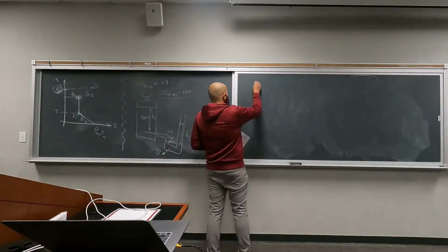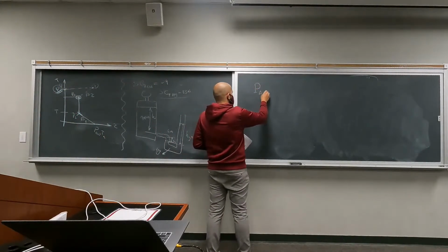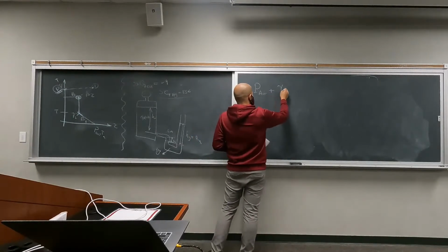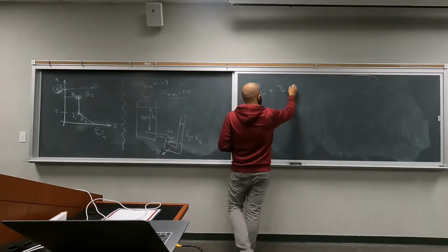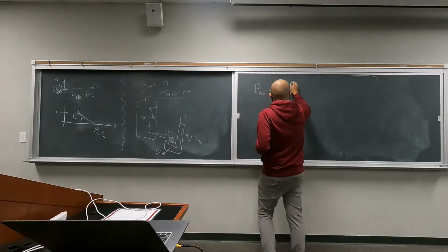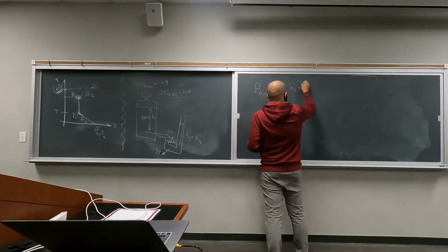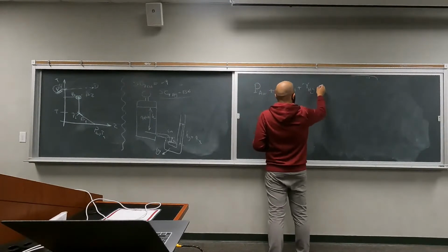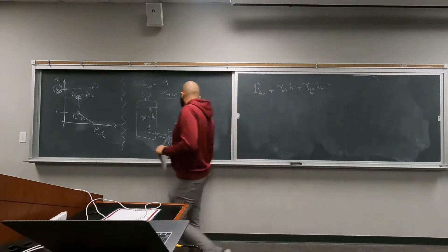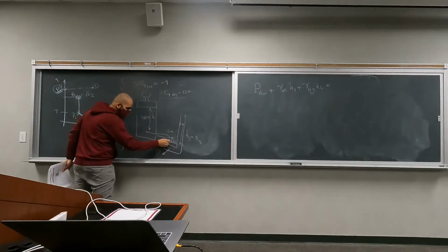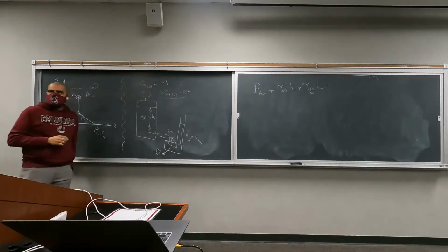So on one side we have P of air plus gamma of oil H1 plus gamma of Hg H2. So that's the pressure at this point here.